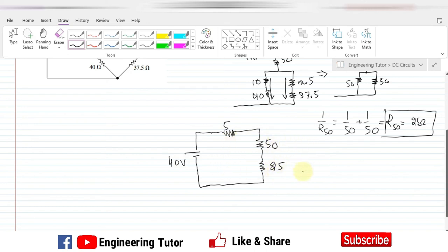And at the end, now these three are in series, so in series configuration, adding them together, we will get here 80 ohm, and this is here now 40 volts. Okay, so this is now our equivalent circuit, where 80 ohm is our equivalent resistance.